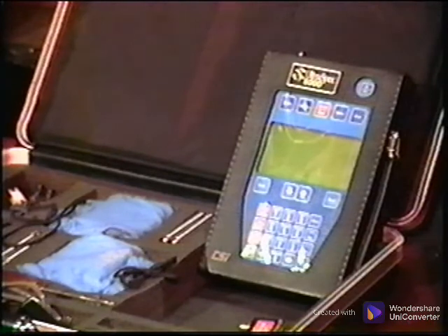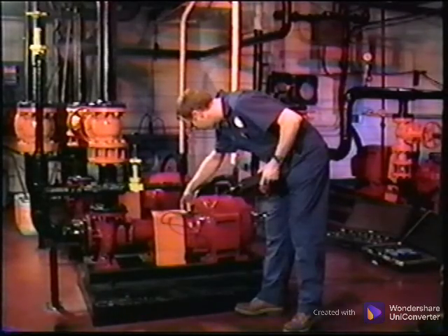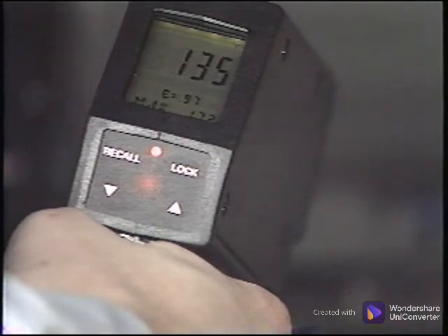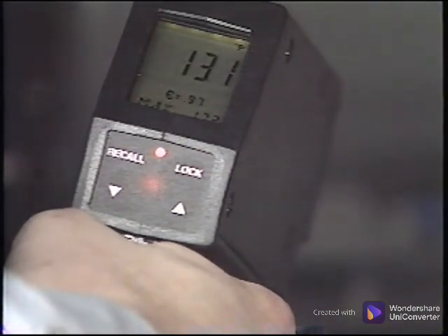Remember to include the vibration analyzer for before and after data, and a device to measure the machine temperature, whether it is an infrared thermography system or a temperature sensor. Collect vibration data and other operating data. Be sure to collect the necessary data to determine the online to offline running condition.